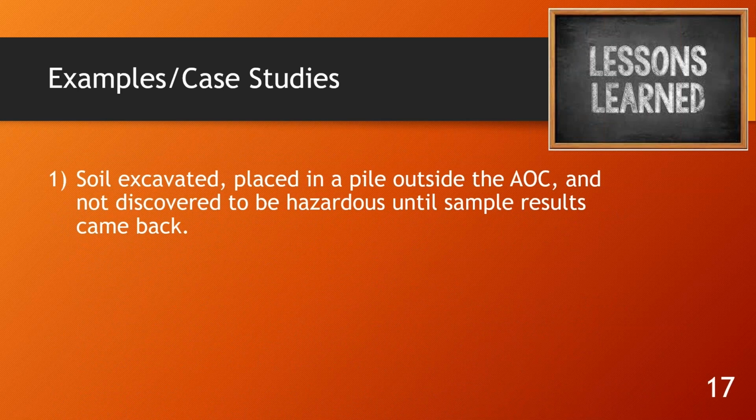Some other examples that I wanted to provide: soil is excavated and placed outside of an area of contamination, but it's not discovered to be hazardous until sampling results come back. This is fairly common, right? Usually, if you have any idea that it could be a hazardous waste, you want to containerize it until you get your analysis back. And by containerize it, I mean it may be as simple as putting a liner down over the soil.